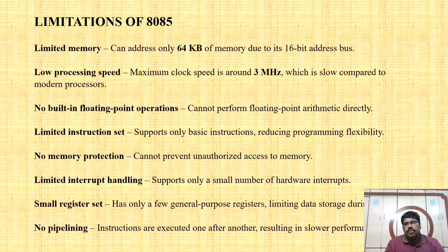And these are the limitations of our 8085 microprocessor. Basically its clock frequency is very low. Next, it is only an 8-bit microprocessor. That means it can process only 8 bits of data at a time, so it is almost a slow one. Next, it doesn't have a proper instruction set. There are only a few instructions, and those are also not a proper instruction set. That means I cannot perform signed operations using this one. Signed multiplications or signed divisions don't give a proper answer.